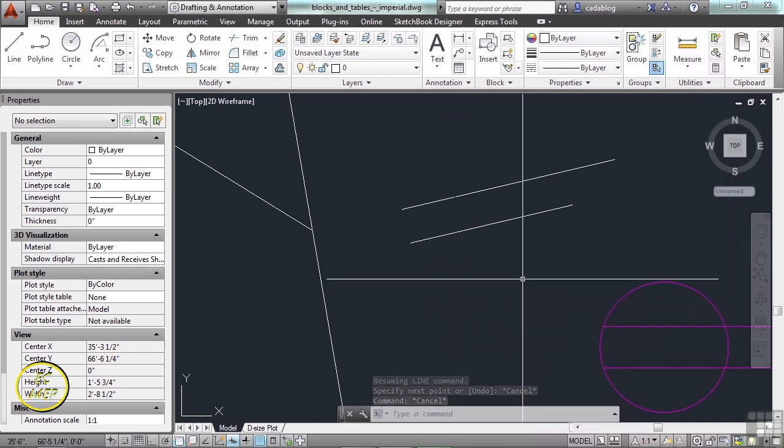I want to talk about what's called object snap tracking. I like object snap tracking. With this, the cursor can track along alignment paths of different objects, based off of other object snap points. And then when specific points are set up, you can use them right in the command. A lot like that apparent intersection that you saw.